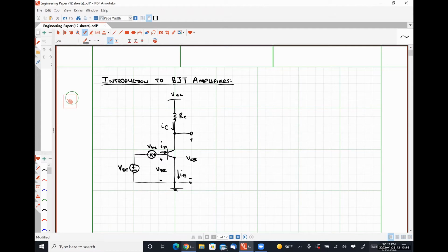And then if I have a mix, so here for iC, iB, this vBE, and vCE, I have a lowercase quantity and then uppercase subscripts. What that means is that I'm looking at a mix of a DC quantity with an AC quantity superimposed on top of it. Okay, so all capital letters, DC quantity; all lowercase letters, AC quantity; if it's a mix, a mix of AC and DC quantities. Are we talking at least the same language here? Maybe not on the same page, but at least talking the same language. All right.